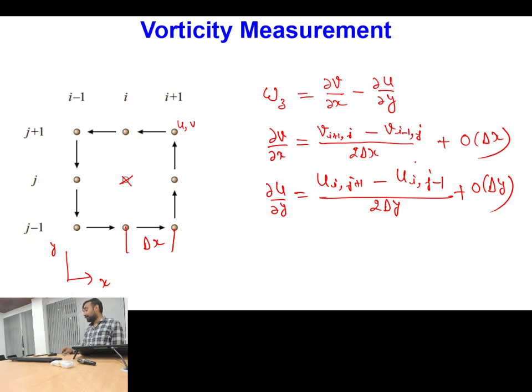So this shows how powerful the PIV tool is. If you are doing PIV measurement, you can know the entire velocity vectors in your visualization window. Along with that, you can also calculate other parameters such as vorticity, deformation, rotation, etc. This is the utility of particle image velocimetry, and in comparison to other methods of velocity measurement, this is more efficient.